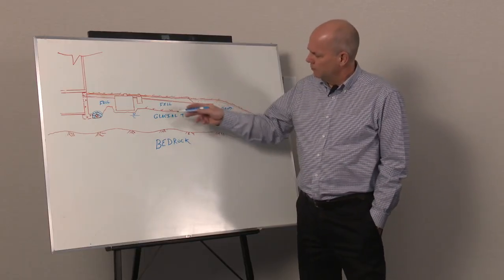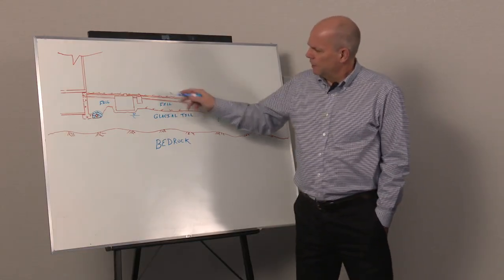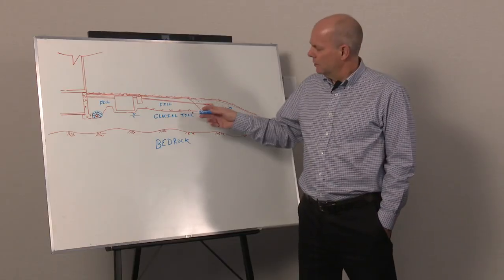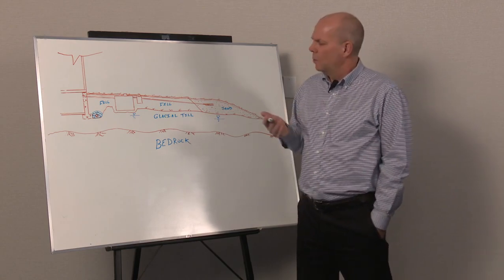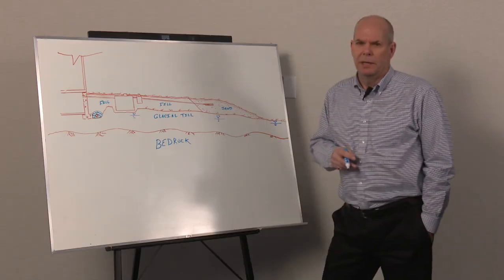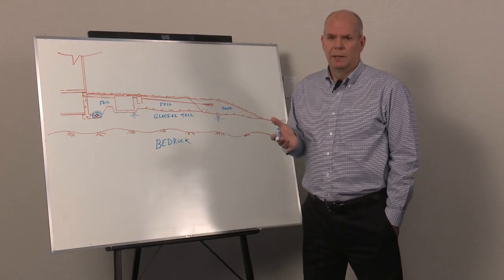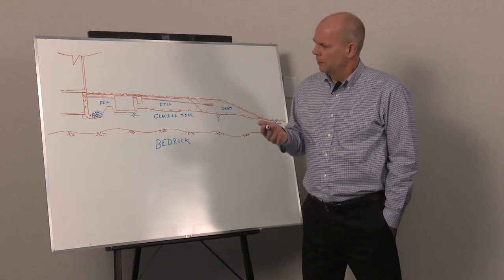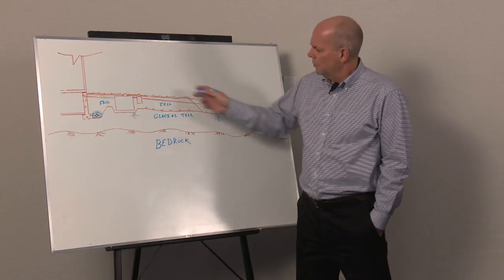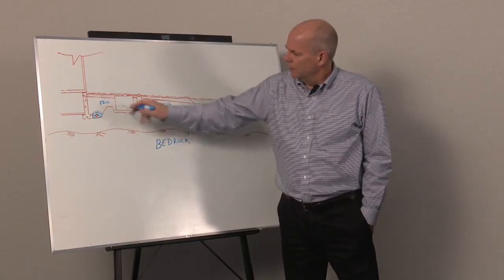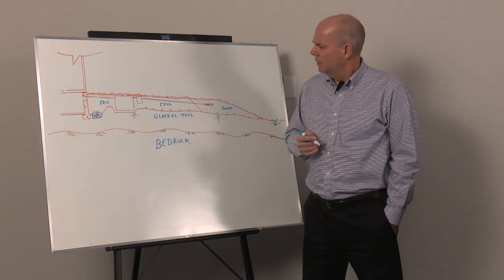Where you get into trouble is when you take this material and use it as a fill improperly. A fill on a site can be almost as good as a glacial till if it's placed properly, or it can be a pile of rubbish. So when you go on a site that's been previously infilled, you should assume that that material is real poor quality, not suitable for much of anything until you do something to determine whether it has been placed properly or not. Most grading of dwellings outside of the building itself will be done with very little compaction, if any. It'll be just dumped, graded, and left.